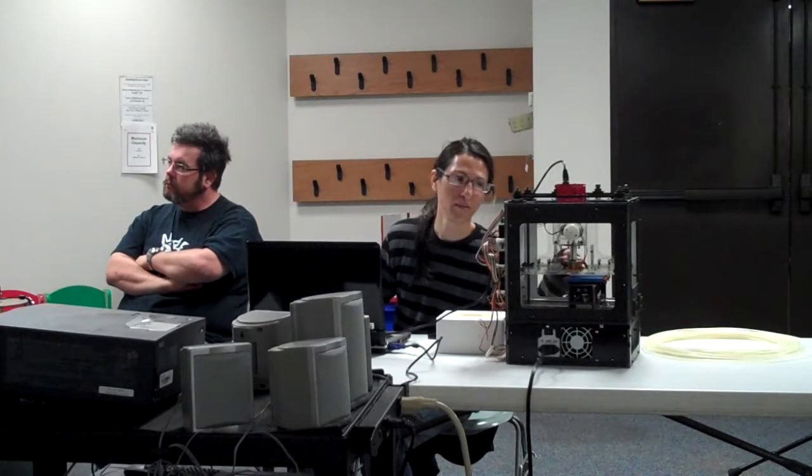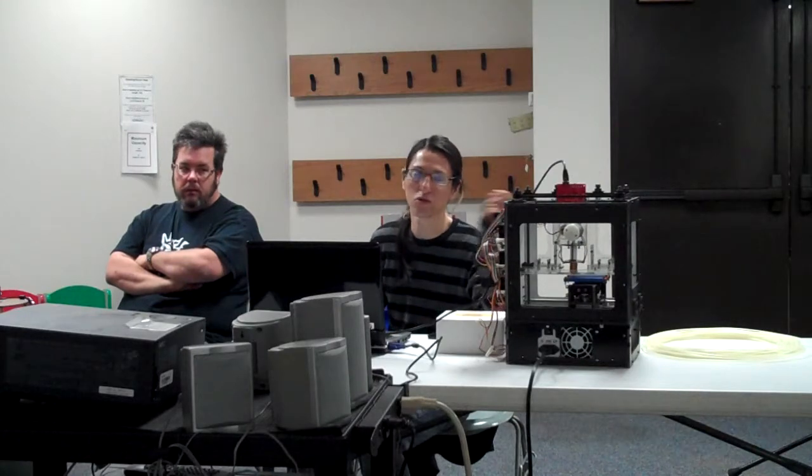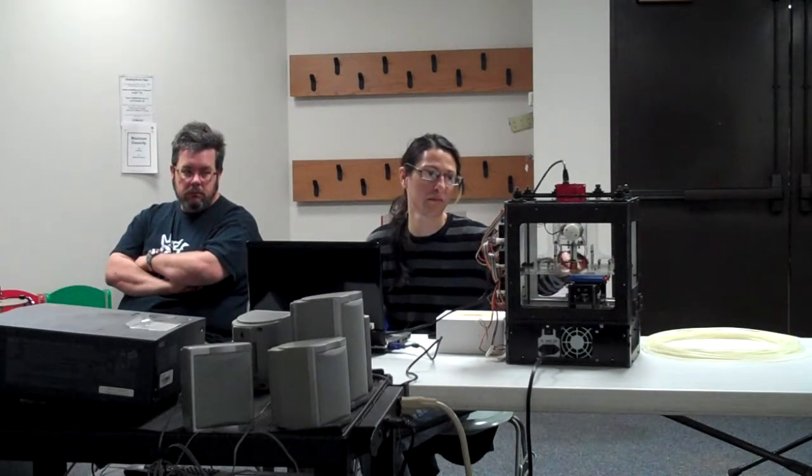Also, the plastic doesn't come out of the head very fast. It heats up pretty quickly, but it doesn't push out super fast. You can adjust that in Replicator G, but from what I've found with the prints I've made, it's better to keep it going slower and you get a better print. The faster you go, the plastic might not have enough time to heat up, and that causes a misprint, because if it's not hot enough, the plastic's not going to come out of your tube over here, and you're going to miss that part in your print.